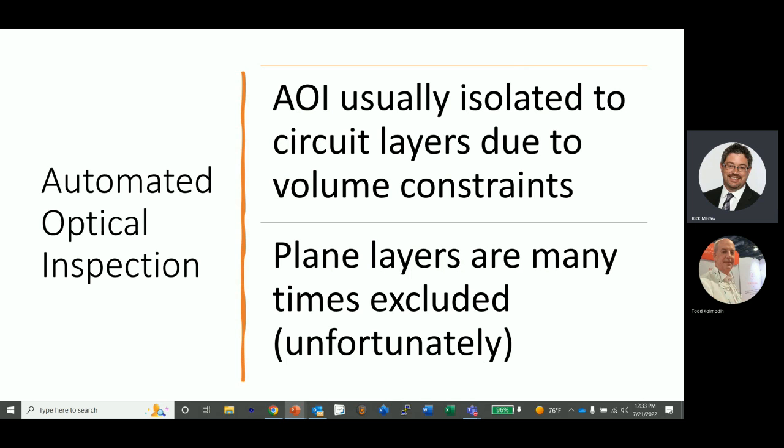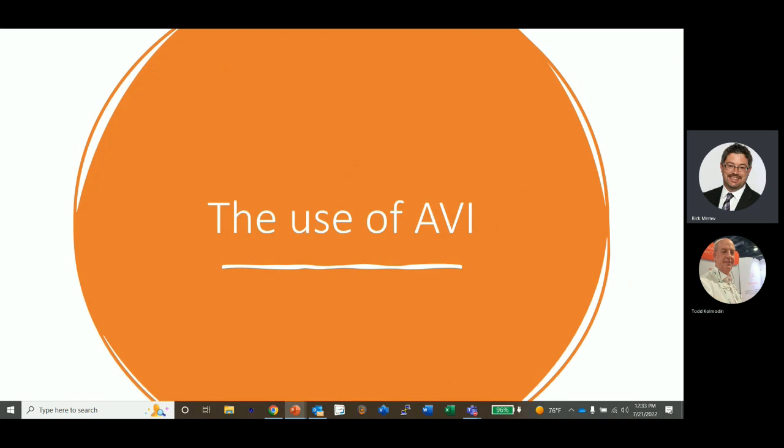Yeah, it's basically the same sort of data that we start with for ET. It's usually production data, which is panelized. It knows for each layer, layer 2, layer 3, what's on each side, where the copper is and what should be there, and it makes a comparison between what should be there and what's not, based on the original CAD data of the one-up. The one-up data is just stepped into a production panel, and that whole production panel is usually programmed into AOI.